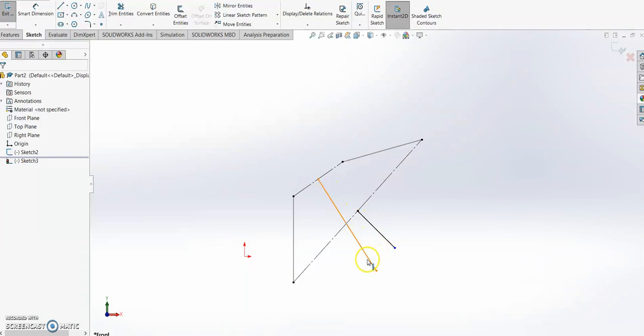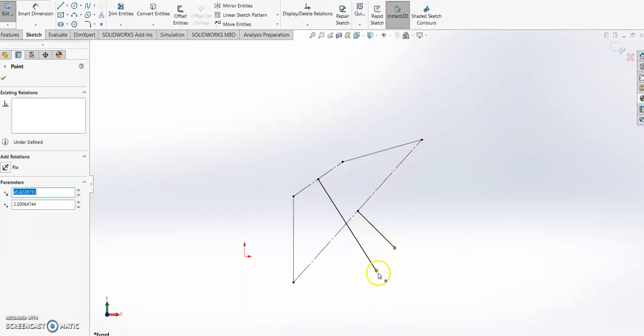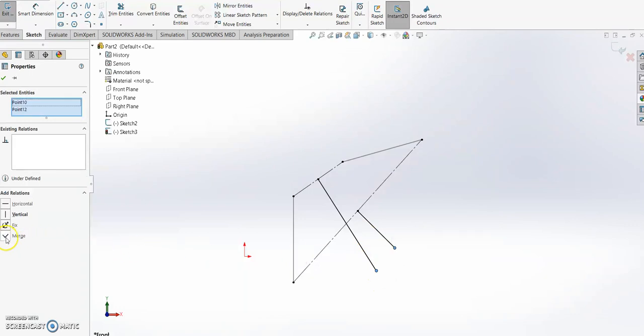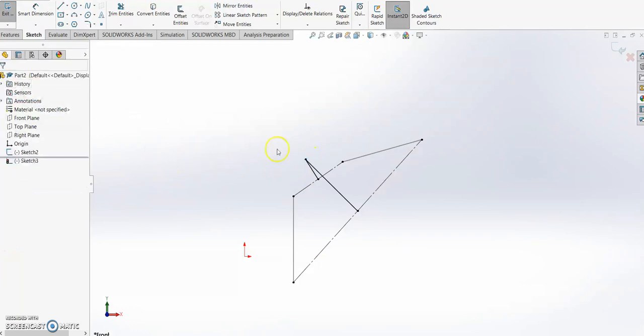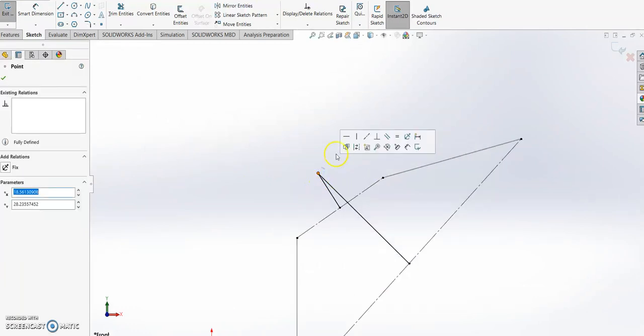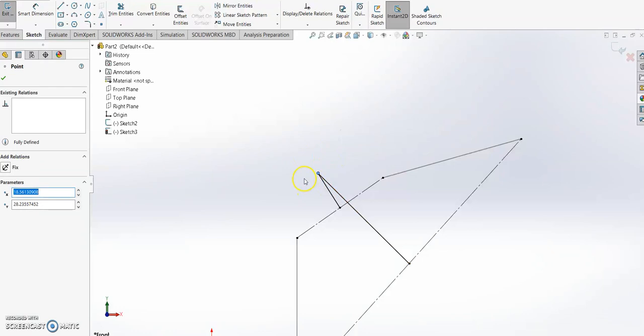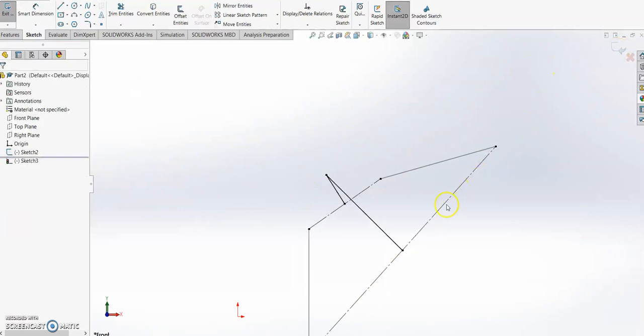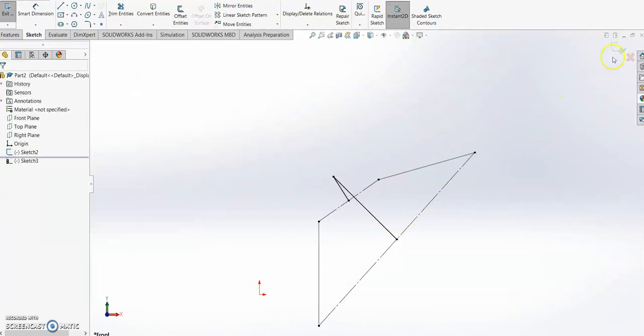You can see here these lines are moving away from each other in this direction. What I can do is grab both of these points and merge them, and that will give me the location of my pole. This point right here is pretty much where all the magic happens in this graphical approach. So now that we have our pole, we can say happy day. We're going to leave that be.